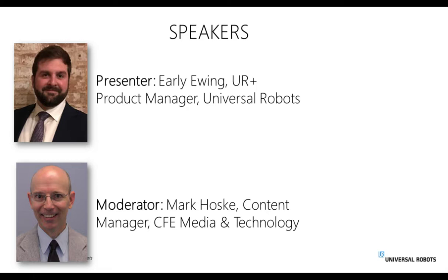Right. What a collaborative robot gives you is a set of features that allow you to implement controls to satisfy a risk assessment. The first step of that, as with any piece of industrial equipment going into a manufacturing facility, is you need to perform that risk assessment. So as far as specific advice, we could take that offline with one of our salespeople or one of our partners. But the point that I really want to drive home is it's a more feature-packed robot than a traditional industrial robot when it comes to satisfaction of that risk assessment, but it does need to be performed.